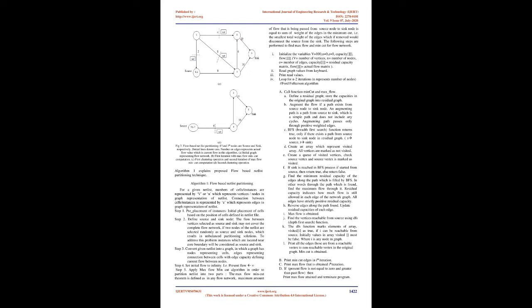The max flow min cut theorem finds a solution for partitioning with a minimized number of cuts for the given netlist through the method of max flow optimization. But this cannot ensure balancing constraints are met. To meet the balancing constraint after every max flow process, we need to cluster the cut edge node/vertex with one neighbor vertex, forming a super vertex. This is done to avoid getting the same solution for partitioning. Once an updated flow network is obtained, another set of max flow computation and optimization is performed.